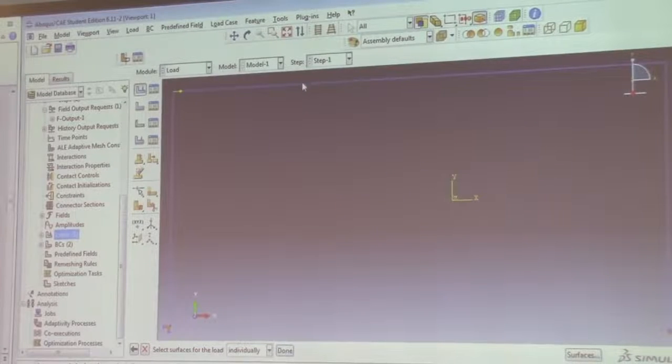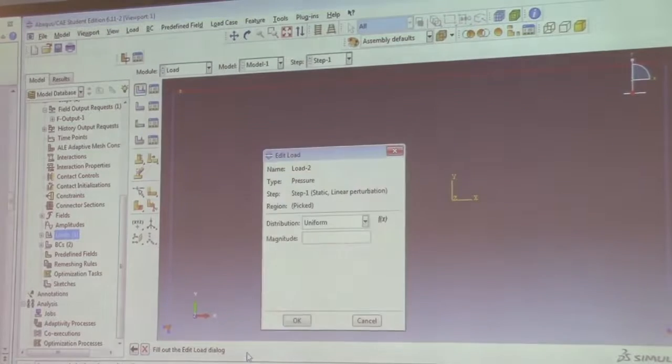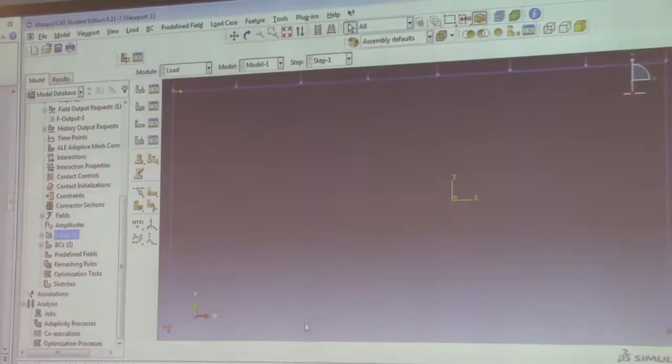Select the surface for the load. So I select this surface. And you can see that you select the side for the edges, either the upper side, magenta, or the lower side, yellow. This means that if I select this side, the pressure is applied on the upper surface, and because pressure by default is applied towards the surface, it's downward. And if I select yellow, it means upward. So I want it applied on the upper surface, and the magnitude is 300. So this is the concentrated force and pressure.